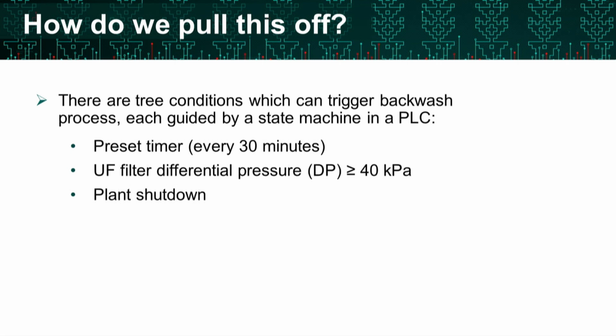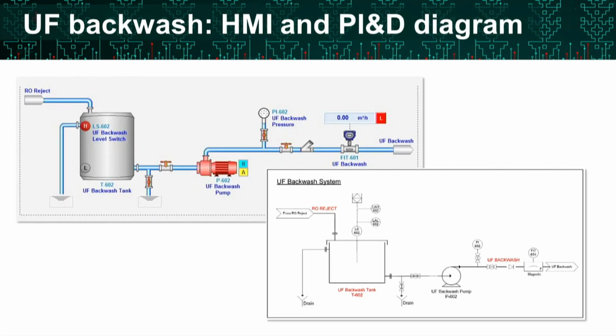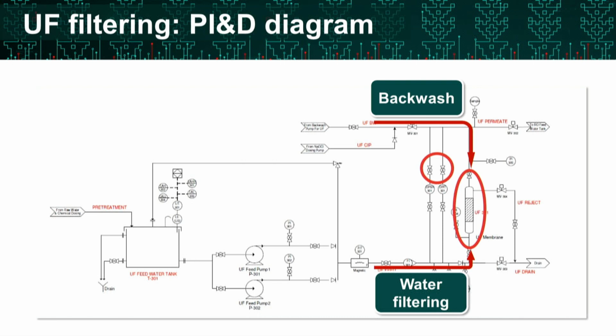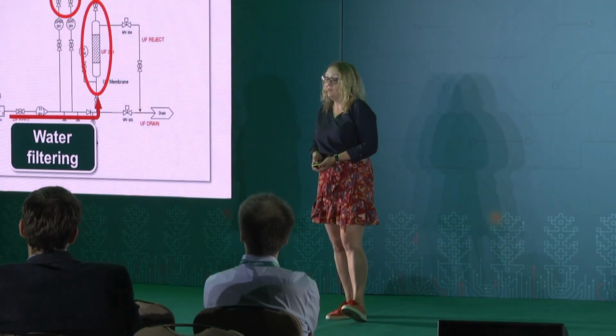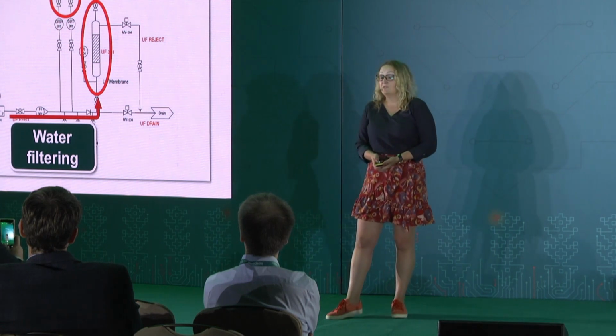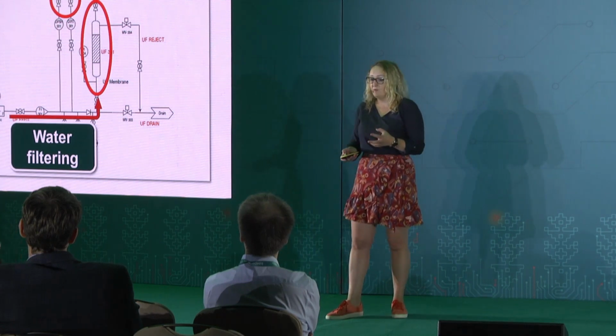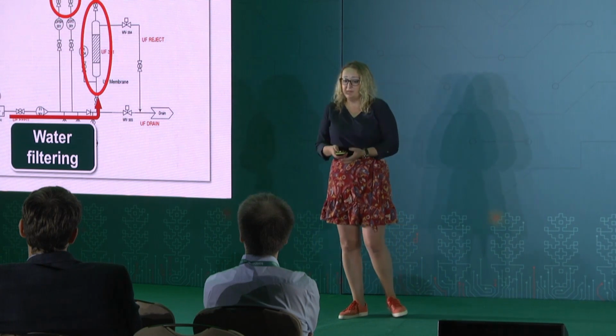And one would think, if I go slightly back, that now it's all easy, we understand. So let's just execute a cyber attack by starting the pumps and opening the valves, and basically we are done, and the water will flow. The problem is we always still have a control layer. The control layer knows that these 2 flows should never happen at the same time, so it will not allow you to do so. So the attacker would actually need to figure out how to prevent this interlock in the control system.